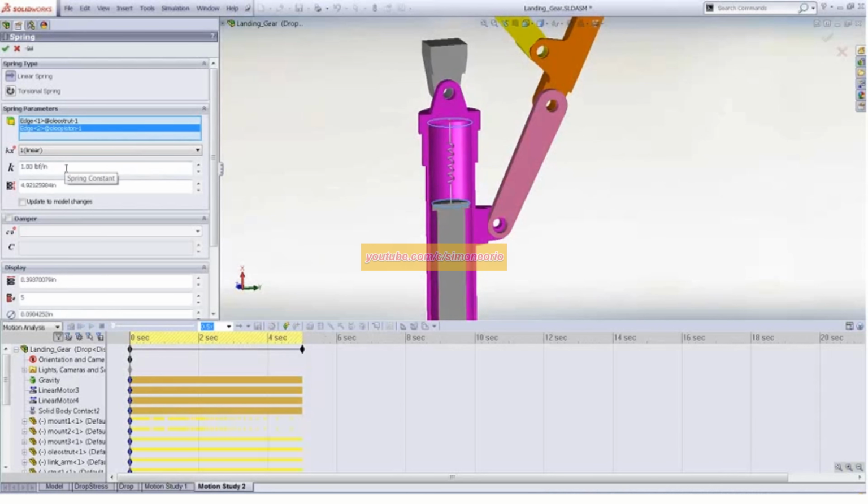And then from here, we can have linear and nonlinear springs. And we can define the length of the spring to create preload. And in this system, we do want to have a damper. And I will also go second order with my damper, nonlinear. And 10% of your stiffness is a good start point for your dynamic system.